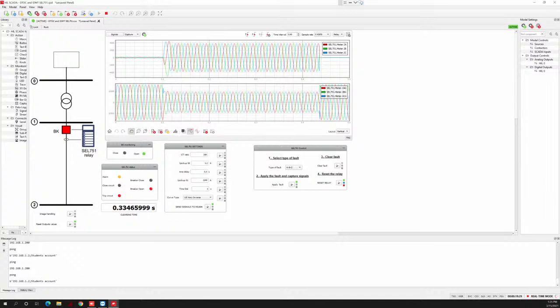There are two basic types of overcurrent protection, okay? There is the instantaneous, that if the current is above a number, it will trip automatically, okay? You can include some delay, and that is what we call definite time overcurrent, okay? But the curve is like this. From here onwards, the time is constant. But there is another overcurrent functionality, and that is a curve.